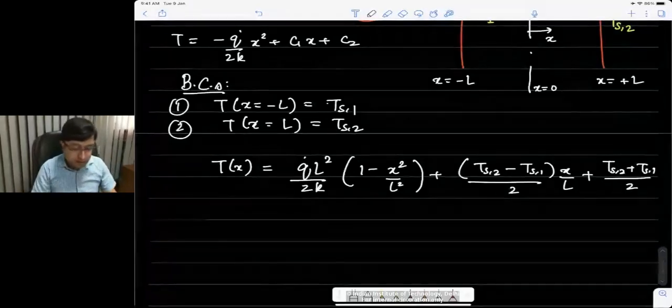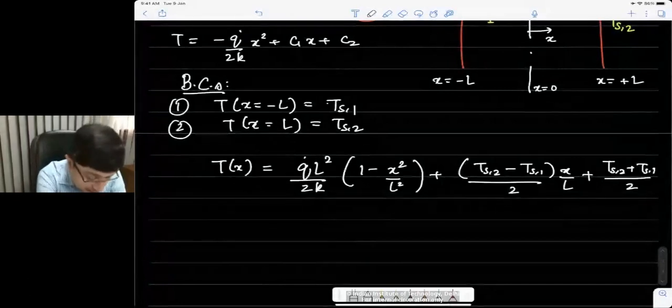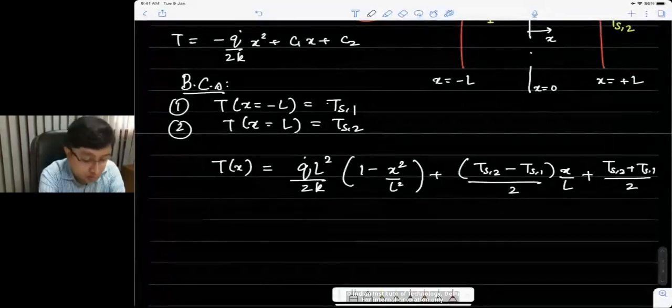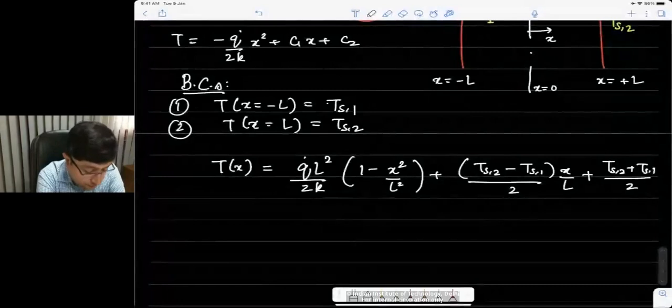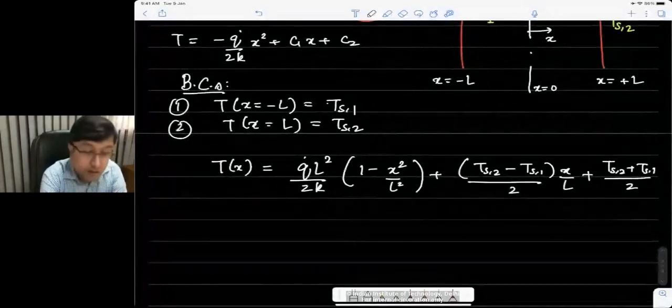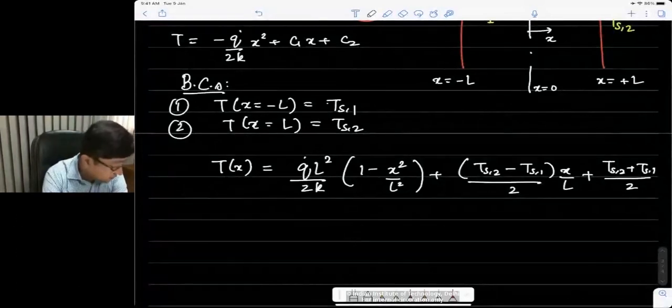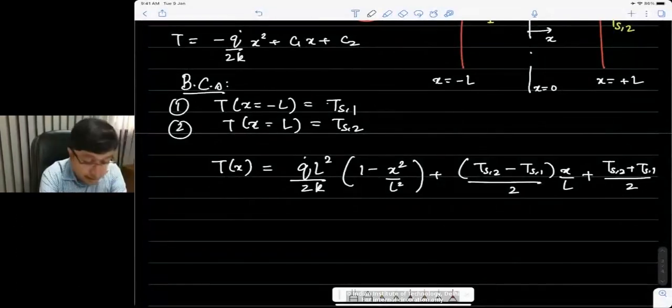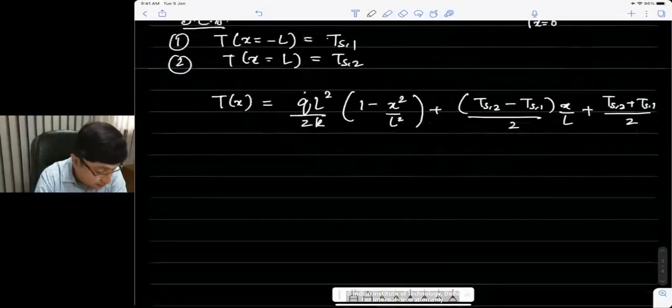And then, of course, the other part is that the flux in this case is not independent of the location. So the first derivative of temperature, when you take it, is dependent on x. So flux is dependent on location, and so that is unlike what we have seen in the case of steady state conduction in a plane wall with no heat generation. Now, the reason I chose x equal to minus L to plus L is for this particular thing that I'm going to cover now.